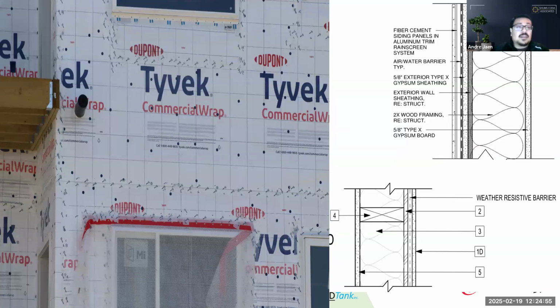So here we go. Here's Tyvek on a multifamily building, right? And right here we can see the tape job that they're doing at every window, at every seal there, at every seam, right? And there's specific lapping requirements for those seams as well. And we should have that ultimately clearly stated on our building plans for what material we're going to be using, right? So we have an air and water resistive barrier that's stated here. Well, air and water resistive barrier points me as an inspector, as a plan reviewer, to have to look at a couple of things, right?